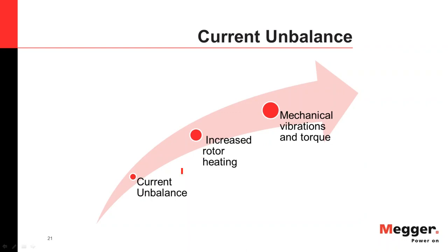And one more thing I would like to say is that the current unbalance scenario was against the nominal thermal curves of the equipment. So it was not following the nominal thermal curves, and that's why it had a large amount of heating beyond the curves, so it was very dangerous to the system.